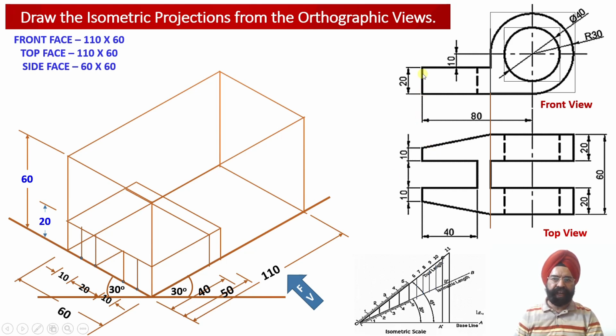And now corresponding to this vertical surface, we know that this web is going to continue towards the rear side of the solid. So now another isometric projection line from this point up to this position over here, parallel to the z-axis, we have obtained over here. Now if we look at the geometry of the object, we observe that from this point and from this point, these 2 projector lines, these 2 vertical surfaces that we have obtained, are parallel to the front face and the rear face of the solid. That is from this point and this point.